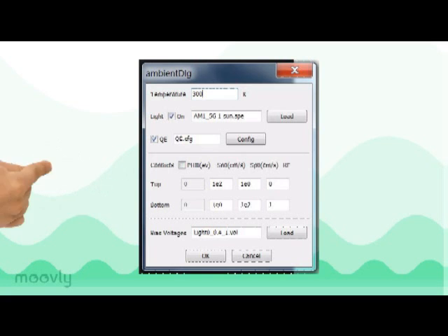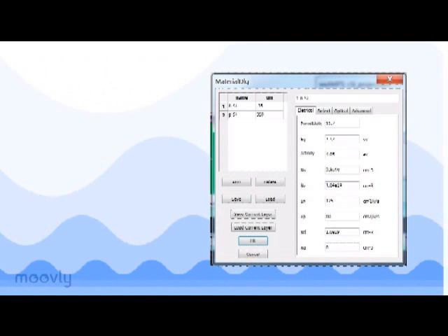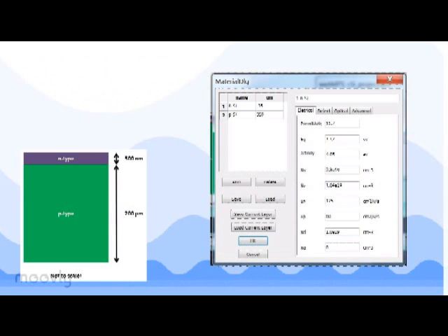Under our Materials tab, I've created a 350 nanometer thick N-type emitter and a 300 micron P-type base, based on the device described by Table 3.2 in the text. For silicon, we have a permittivity of 11.7, a band gap of 1.12, an electron affinity of 4.05, density of states for the electron and valence bands on the order of 10 to the 19th. The electron and hole mobilities are different for the N and P type based on the doping densities.